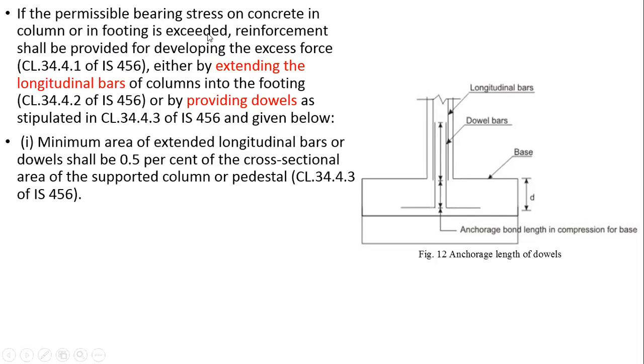We have a failure. So in that case, reinforcement shall be provided for developing the excess force. For that excess force, I have to provide some extra reinforcement as per the clause, either by extending the longitudinal bars of the columns into the footing or by providing dowels.